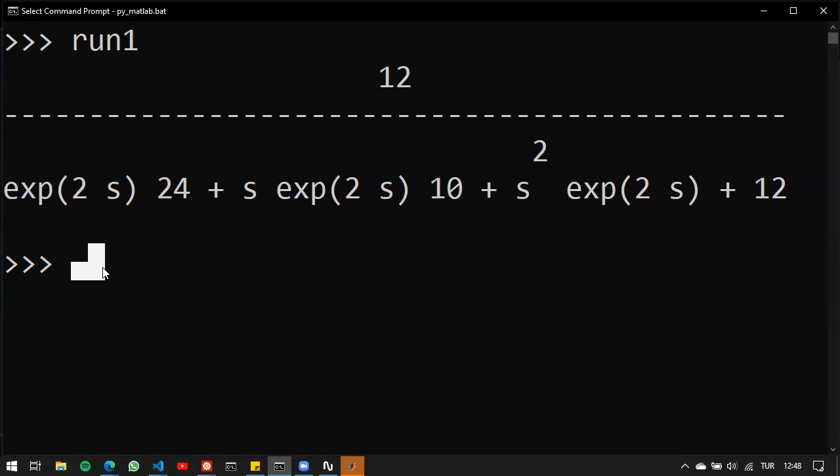But there's also another possibility that will come up in the upcoming lesson in the laboratory session. That would be to use frequency domain methods, because I can plot the Bode plot of this. So if there are controller design methods using Bode plot, then I might use this transfer function, its Bode plot, to design a controller. So that might be one route, or you should approximate e to the power of minus 2s in this case. So next lesson, we will see how to maybe do that or talk about the frequency domain methods. You can then apply all of those things that we will talk about to this transfer function.